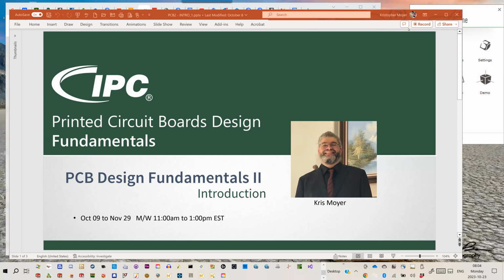As you heard, Matias had a few questions. His first question had to do with when you're actually routing, and we're going to talk about this a little bit more, probably this Wednesday when we get to some more hands-on with the tool itself, since we only got to creating the design rules last week. But SMT pads, through hole pads, do's and don'ts of how you route the trace into or out of the pads. The two main rules are no acute angles and no reducing of the clearances between the pads. So those are our two main rules that we're going to follow there.